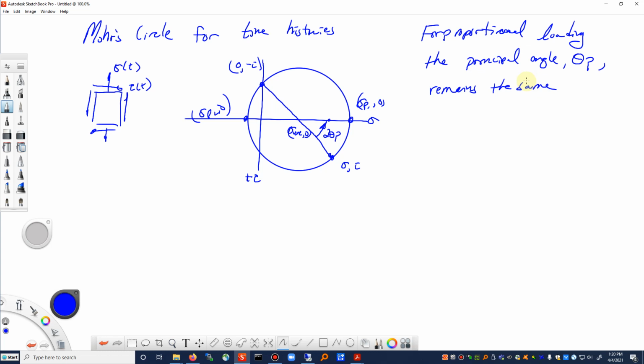Now from a fatigue perspective, this is kind of handy, because your cracking orientation, all the main damage, if you think of the principal stress causing the most damage, all of that is occurring on one plane, or your maximum shearing stress if you're looking at more initiation type loading. For non-proportional loading, the principal stress directions can change with time.